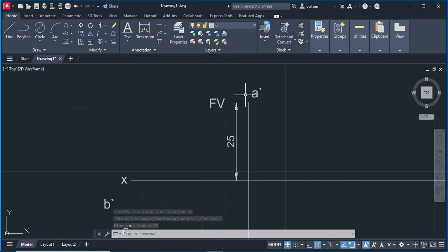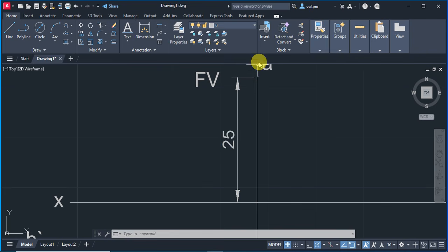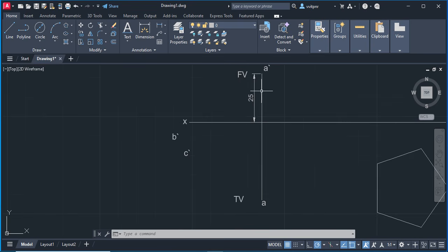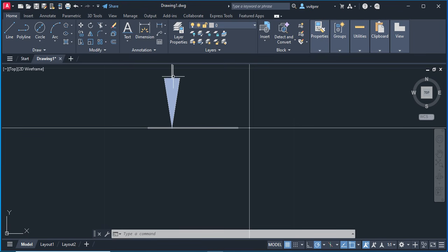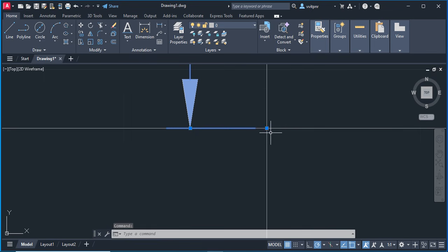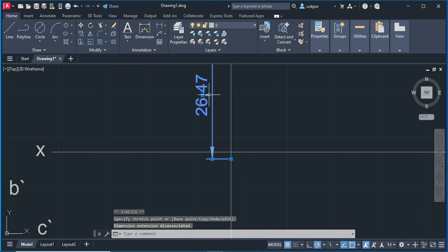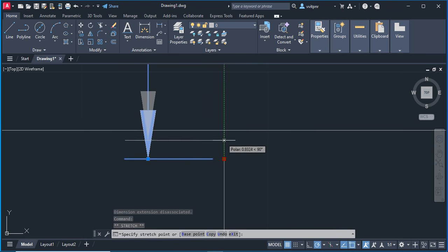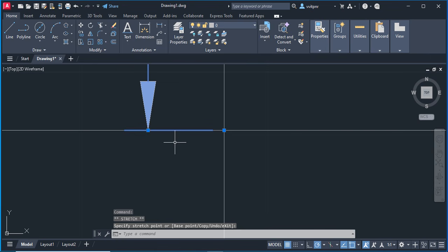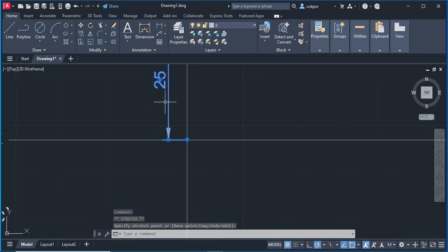Now you can see, while I am giving the size, I selected this point and I selected exactly this point. The selection is also very important. Suppose this is a dimension. Select this one. Now it is 25. It was located from this point. When you select somewhere else here, see, it shows a different distance because you selected a different point. So exactly we can select this one. If you mark it wrongly, simply you can click and drag to change it. There is no need to delete also. Now you can see here it was showing 25. So these precautions we have to take care of.